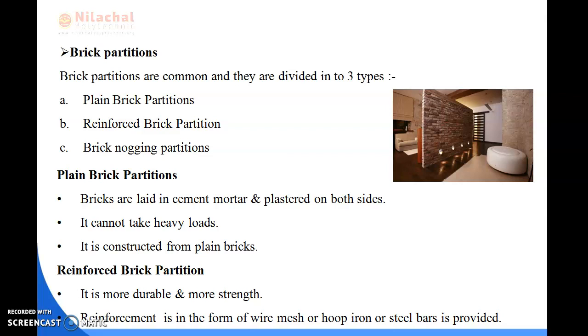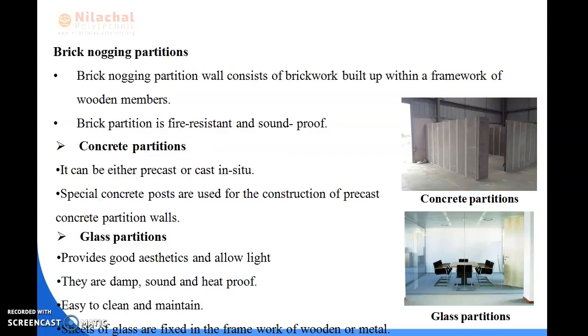Next one is reinforced brick partition. This reinforced brick partition is more durable and has more strength. Reinforcement is provided in the form of wire mesh, hoop iron or steel bars in the brick.